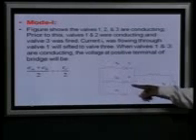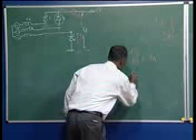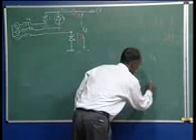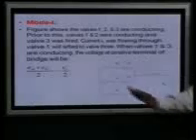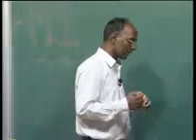Similarly, I can write for this circuit as well, EB minus L di3 by dt will be your VA. We are assuming the L is constant in all these three. Again, this is an assumption, but L, the inductance offered by this transformer, is the same in all three phases. Now, simply add it.